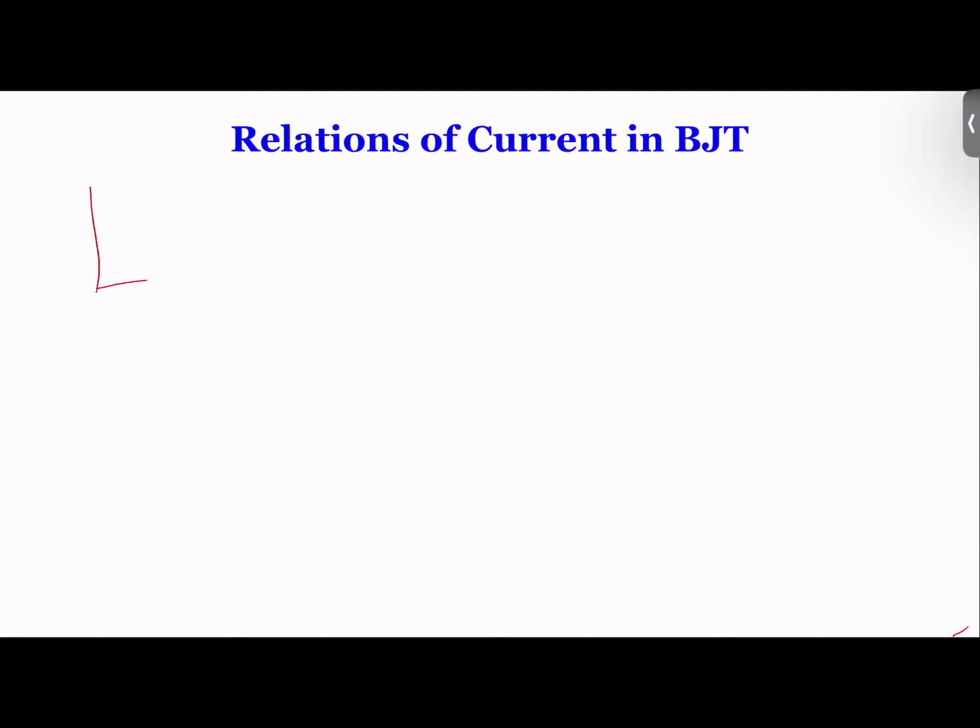So if you remember the curve that we had for the MOSFET, we call this one the triode region, and this one the saturation region. The corner area, where the current changes as you change VDS, is called the triode region. When you move on to the flat portion, where the current is constant for a given VGS, that's called the saturation region. In electronics, we mostly use the saturation region for the MOSFET.